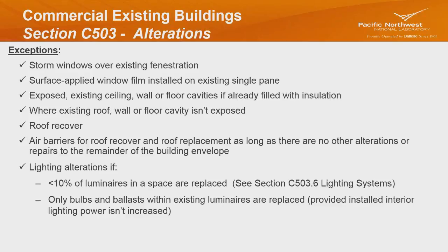All right, so where the existing roof, wall, or floor cavity isn't exposed, what does that mean? I'm exempt. Does that mean I have to submit something to the building department? You should. You're telling them that you are doing some alterations to a building. However, I'm exempt from having to meet the provisions for putting more insulation in those assemblies for the building thermal envelope.